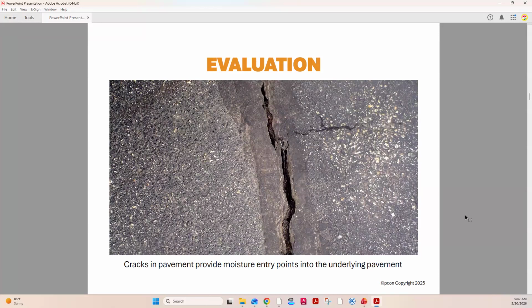of your asphalt pavement. So we're looking also to see this. Here's an example here. This has been crack sealed, obviously, in the past more than once, but we're at a point now with this pavement where the maintenance of crack seal or seal coat is no longer going to benefit this pavement, and it is time to do a repair, a major repair on the pavement.